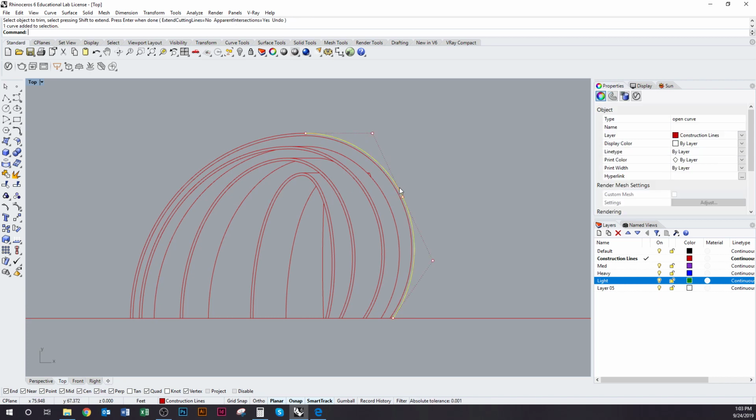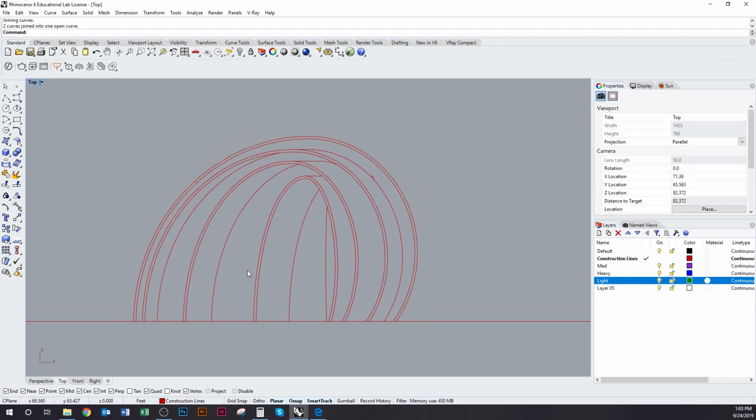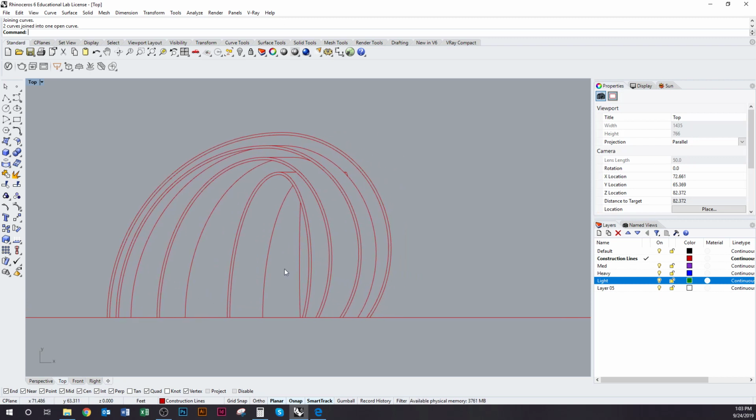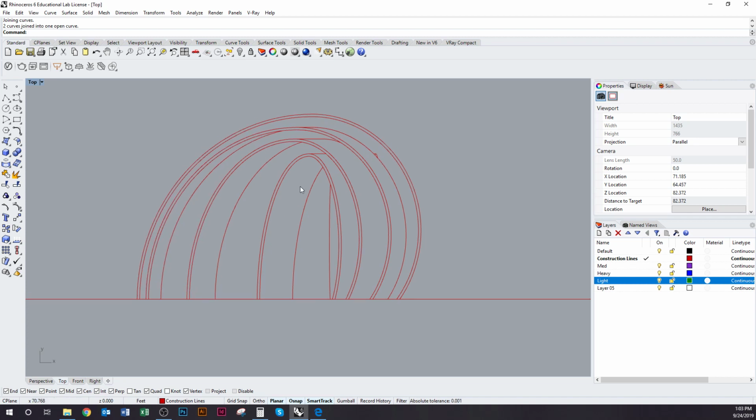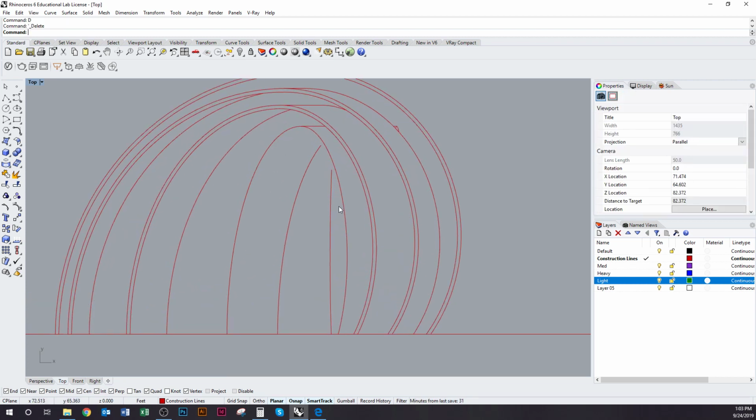And I think it's a good point of reference when doing orthographic drawings to try and do as much as you can with line work before you move on to using things like poche or shading and multimedia, things like collage and stuff like that. So even though it's starting to become clear how this object works three-dimensionally, and actually I'm going to set this one again.